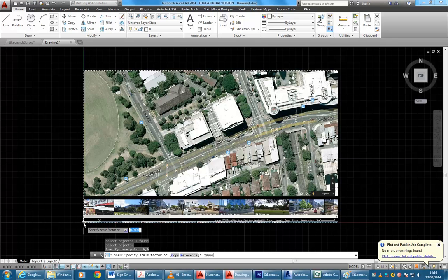And then divided by 21.5 is what I want to type. I want that value, but AutoCAD won't accept decimals in a fraction. Okay, so all I need to do there, so I can use that number, is multiply them both by 10.